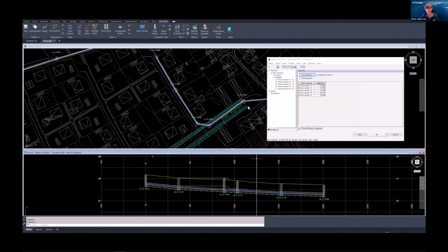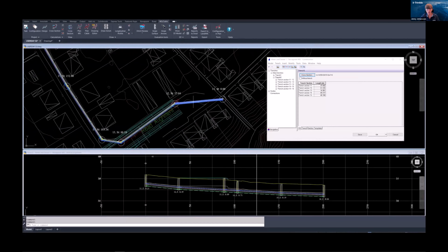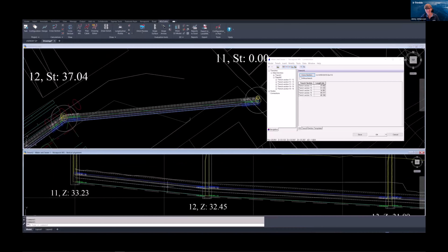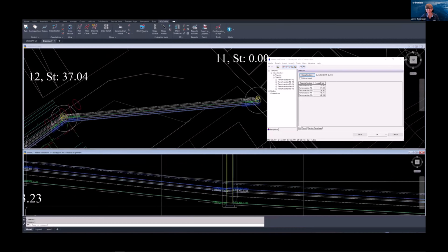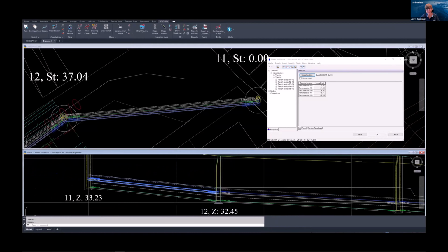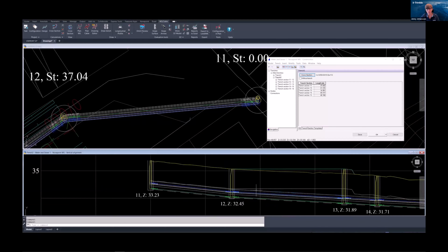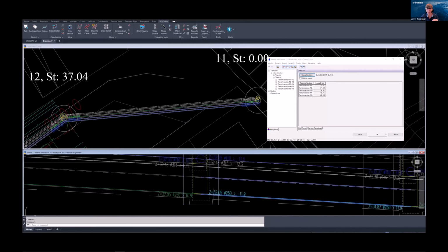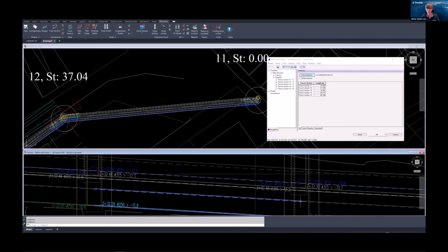What we can see now is that we have 4 pipes. And if I move to the vertical drawing, we can also see that there are double connections, even though they are in the same elevation. What we need to know when choosing a new cross-section for a whole trench is that all set values for manholes and pipes are reset to default heights.